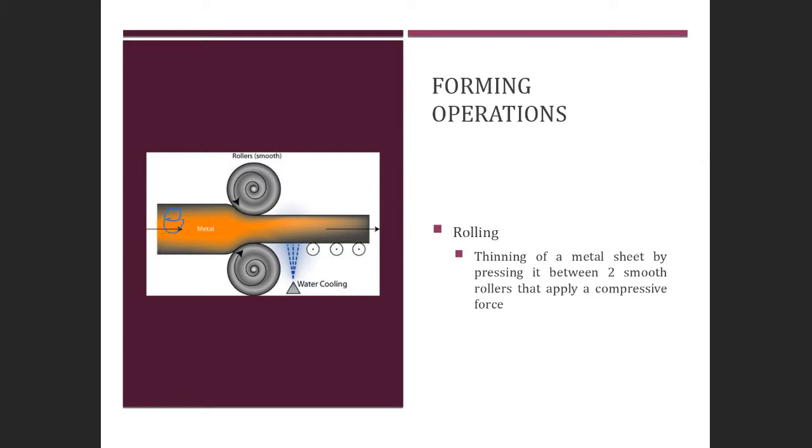Then when it goes into the smaller cross-sectional area, the grains are automatically deformed, in how this material is being smashed together. But because of the heat being above the recrystallization temperature, the grains right at about this point will become smaller but equiaxed. So these are all going to be equiaxed grains here.